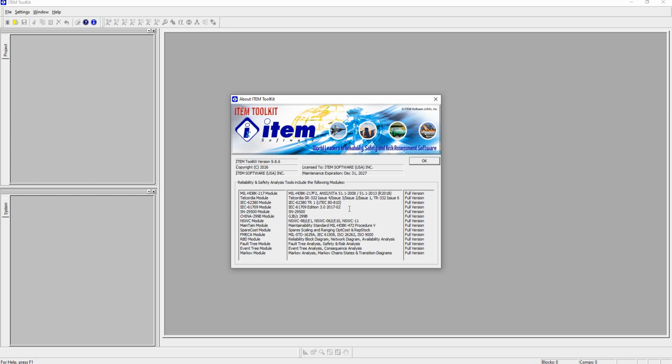models. We looked at the results summary for our FTA and in particular the cut sets for our FTA system, or the combination of events happening or components failing that could together satisfy the top event, and the unavailability or the probability of an explosion over the system lifetime or study time of 8,760 hours.